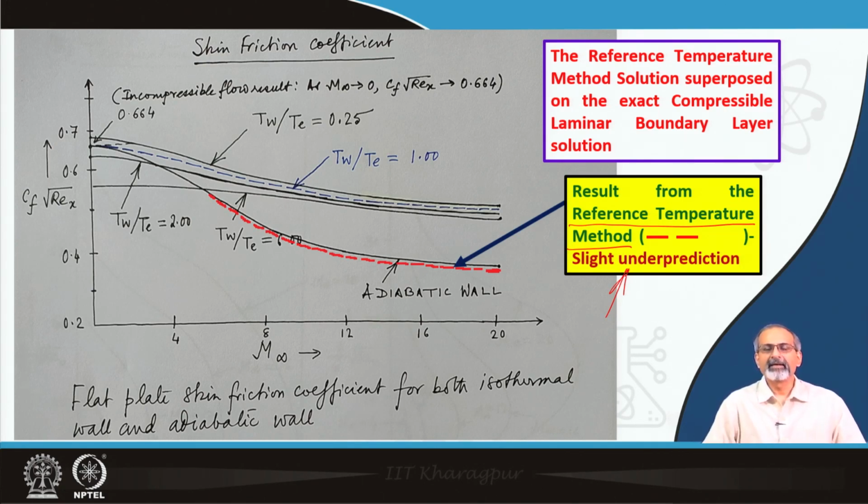However, remember, it is based on certain simplifications. We essentially invoke the incompressible flow results, and we assume that the boundary layer remains a non-reacting layer. If you want to bring in those realities further into the calculations, then perhaps you have to extend the models and bring them in, which could be your research problem too.